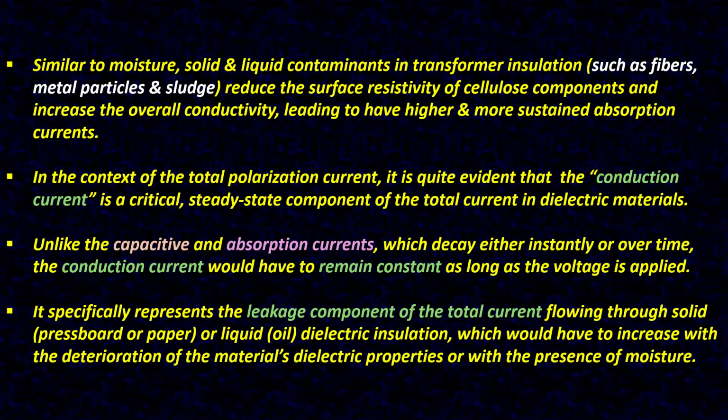In the context of the total polarization current, it is quite evident that the conduction current is a critical steady state component of the total current in dielectric materials. Unlike the capacitive and absorption currents, which decay either instantly or over time, the conduction current remains constant as long as the voltage is applied.